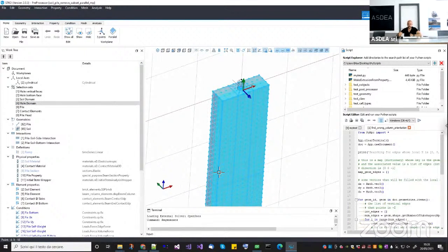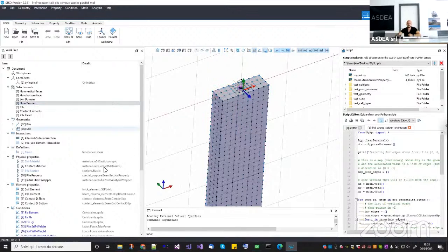contact elements there. Probably one solution can be to apply the contact elements after the removal, and before the removal, they can be an equalDOF, for example. That can be a solution. You can try to play with it anyway. So first question, yes, the new contact element will be compatible with any kind of offset.